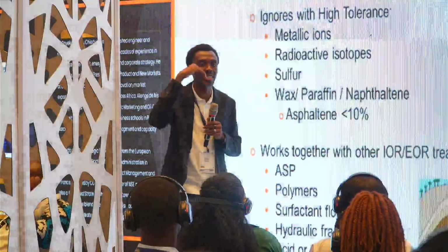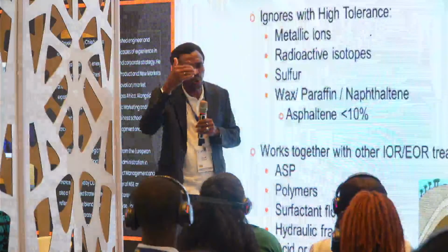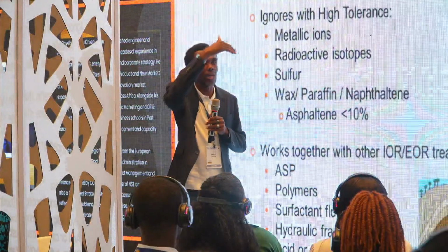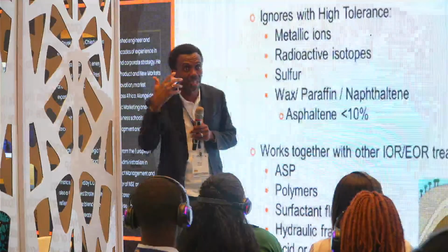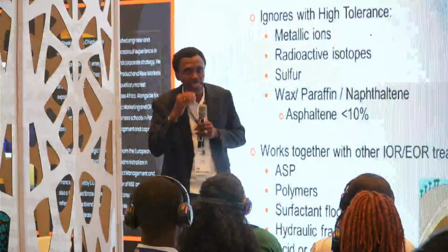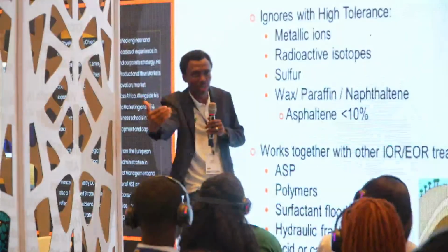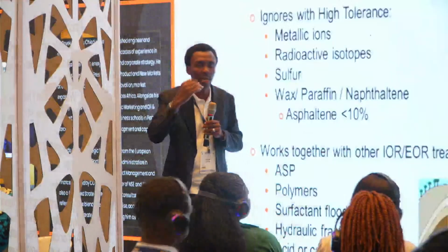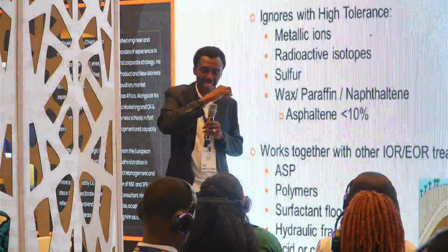Why it's called skin stems from the fact that it's supposedly just a small layer, but because it happens across maybe a 100-foot perforation, its impact is always large. It's just on that surface. By the time you add a little acid, it might just take it off, and as such have all your crude oil come out of the formation. It can happen.